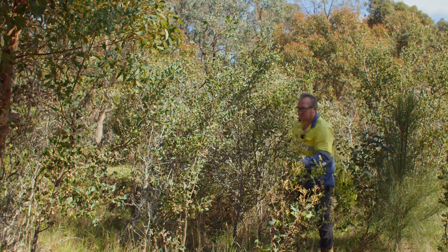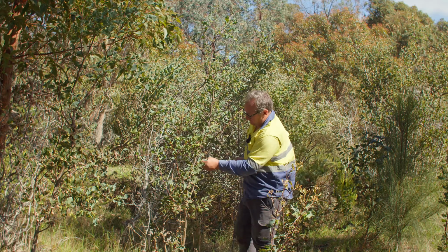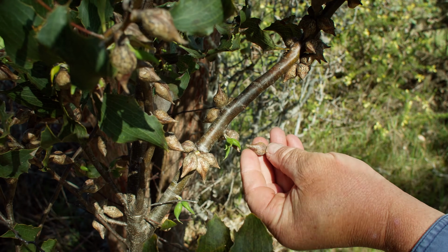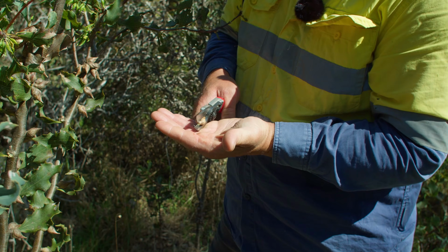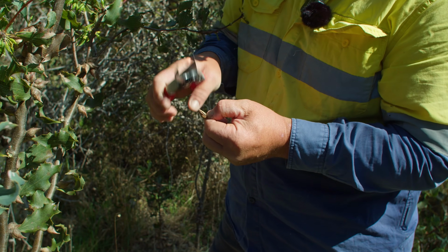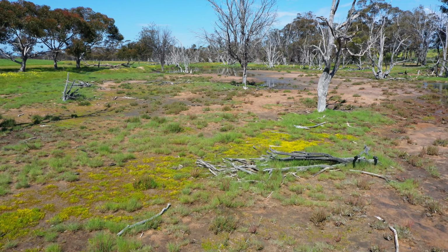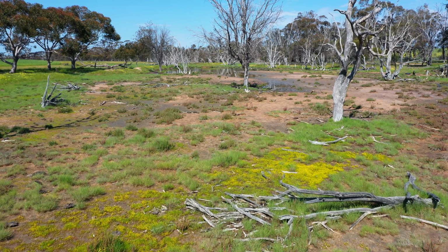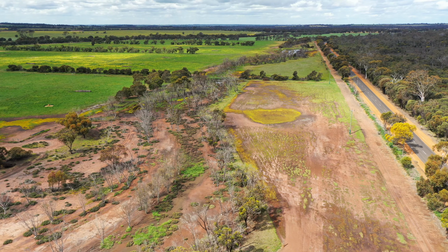And this is what we did at the Katanning Research Station. We did an on-ground site assessment. So we walked onto the ground, kicked the dirt, so to speak. We did dig test pit holes to look at the soil profile. And we also noticed that there was barley grass scald areas, which is a good indication that there's a salt presence in that area.